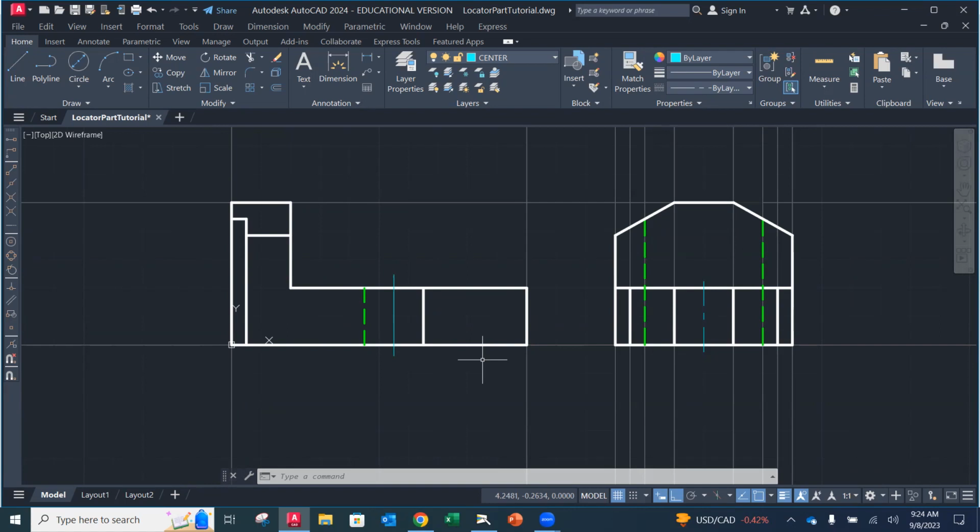No. What that means is the size of the line and how the spacing is standard is too small or large. We'll have to see for what we're drawing at. Okay, and that's okay. We can deal with that. So what we're going to do is we're going to exercise a command called LT scale, line type scale. All right, line type scale. So if I go down here and I do LT scale, line type scale, enter.